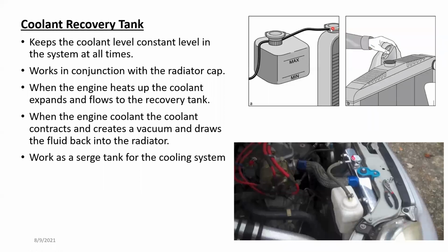Once the valve is completely open, when it is having high pressure, the liquid coolant is coming back here. So if it is over the max limit, it will come up and fill it up to here, right? Then once the pressure drops again in the system, when the engine is completely turned off and the cooling is happening, the coolant is sent back inside.